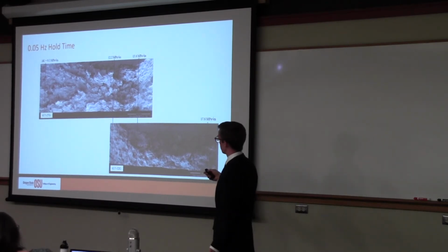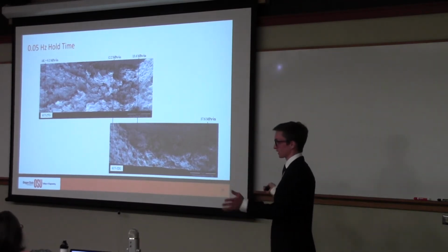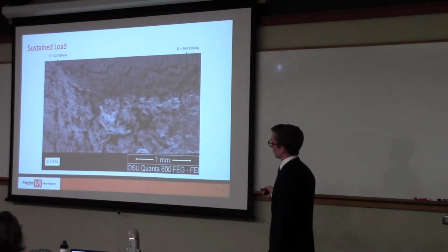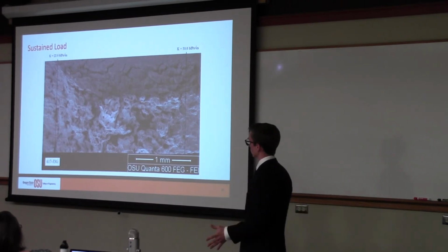And what do we really see here? That there's a mechanistic shift right around 12 megapascal root meters delta K. Same mechanistic shift happens, maybe 12, 13. There's a good enough agreement with these 2 samples to say that's where the transition happens, that's where crack growth rates increase.